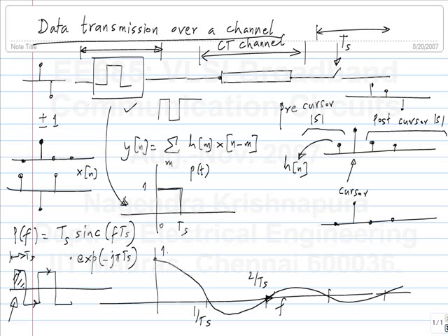Any signal can be represented as a sum of sinusoids, and the relative strengths of sinusoids are given by the Fourier transform. And in case of continuous frequency variable, you have infinitesimally spaced stuff, so you have to integrate it, not sum it, but that's a detail. So this means that the amplitude of the sinusoid at fs, 2fs and so on are 0. How do you calculate the Fourier transform?